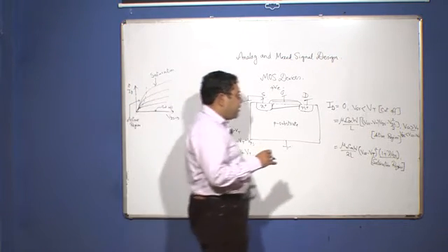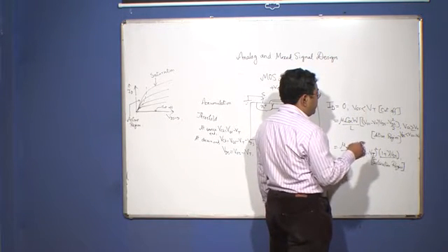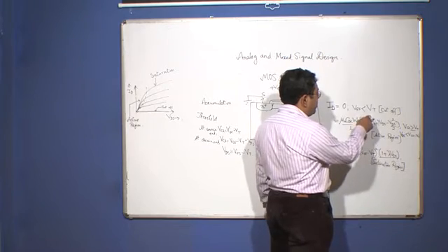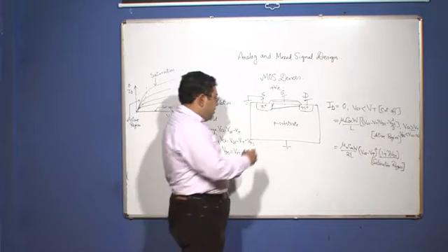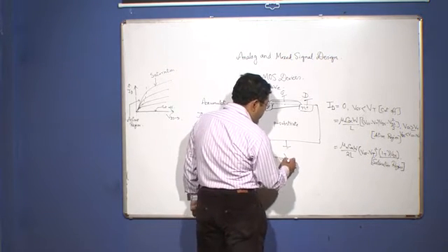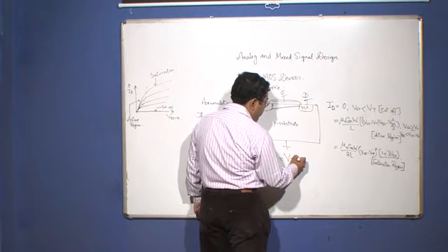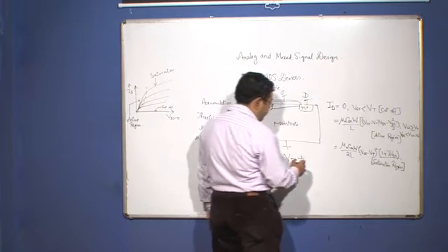Now you could see one very important thing, that is the notion of threshold voltage. You need to give a minimum of threshold voltage to turn on the MOS transistor. If you see the equation of the threshold voltage, you will see that it is dependent upon some parameters.